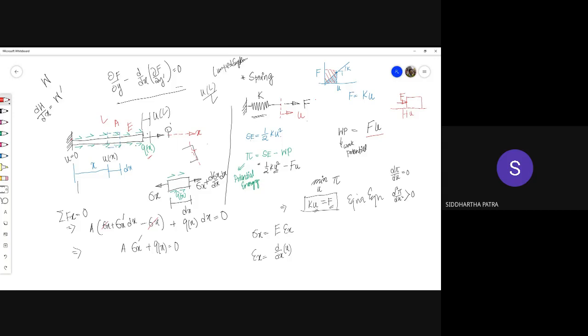Wherever you take the free body diagram, it is just P versus P on either side. So stress is the same, which would mean the strain is also the same. But if it has a distributed load, the strain is not going to be the same, and hence strain requires a differential definition. Which means I can only define strain